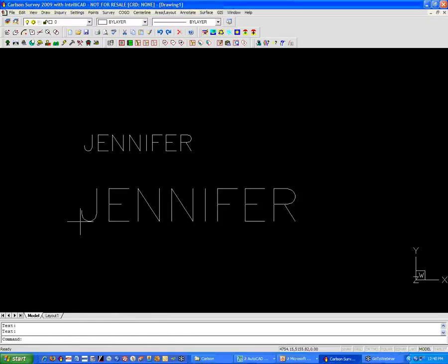So now what happens when I go to add text? All right. I'm going to do a DT or dtext again. Pick my starting point. And trust me, this is exactly the same in AutoCAD or IntelliCAD. This is the difference between having an assigned text height of 0 versus an assigned text height of something greater than 0. If I have an assigned text height of 0, it's going to ask me every time what my text height is. So if I need text height of 10, I'm going to do that, and I'll type it in. Now what happens if I need a text height of 20? Well, I'm going to go back into dtext, pick another point, but this time I'm going to have to manually type in what that text height should be. Okay, so those are the two different methods of setting up text.